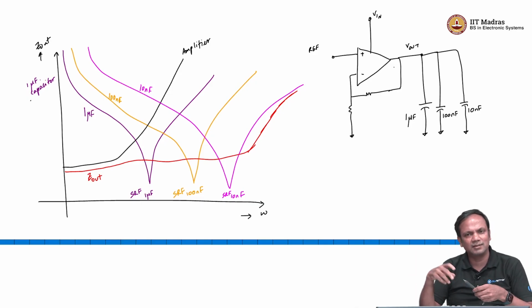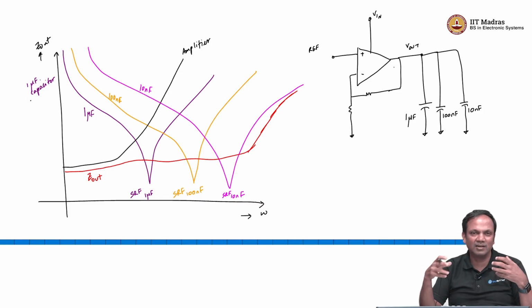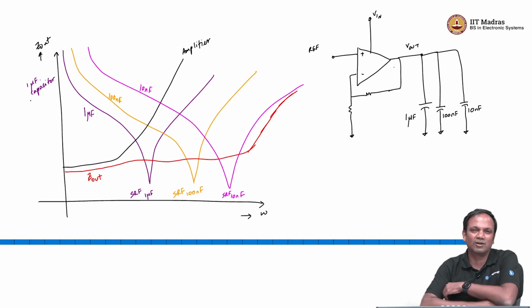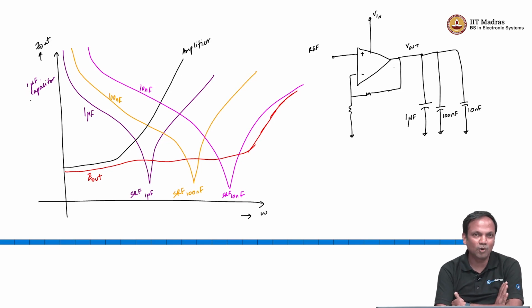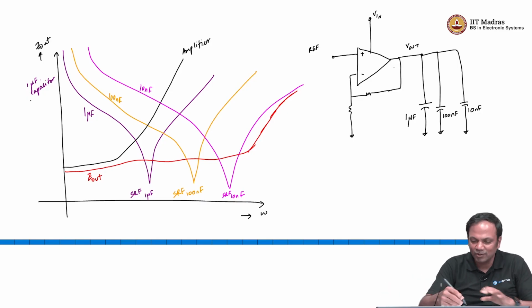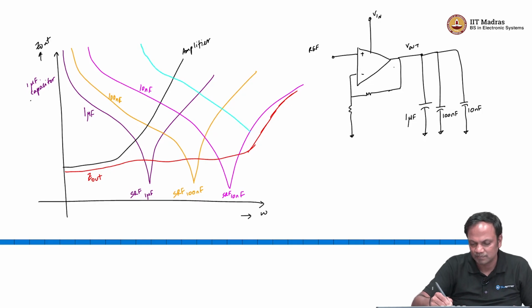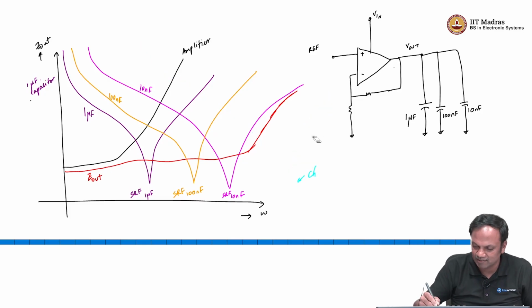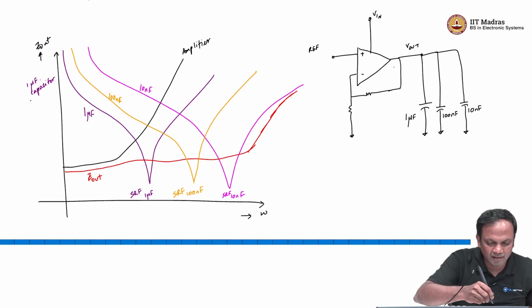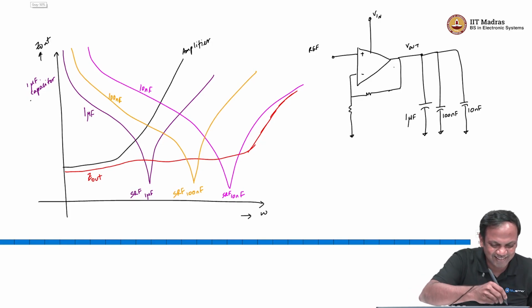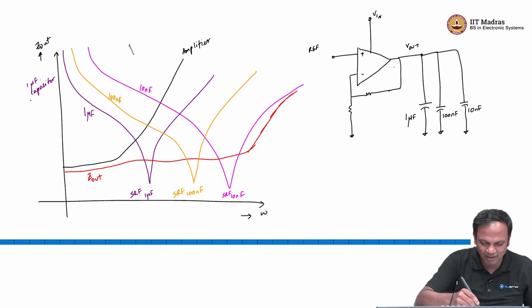Now, it might so happen that the chip itself has about a nanofarad of capacitance. Nanofarad is large, but it is possible if it is power intensive like a microcontroller, it is a reasonable chance that there is local decoupling on the supply in the chip. So, it might so happen that while the LDO does all this, you might get help from the chip, where the chip has a 1 nanofarad capacitor. Let me take a darker color, running out of colors here, let me see, olive maybe.